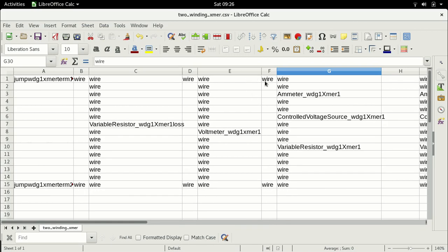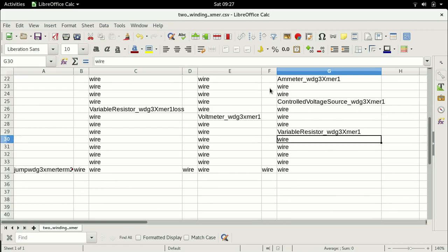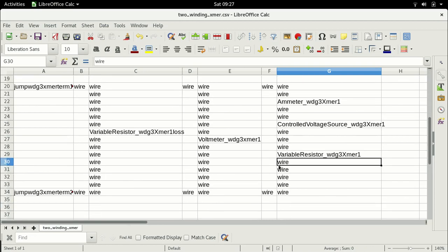Now, when the switch is turned off, the current will try to stop flowing, which means the induced EMF will oppose the cause which produces it, and that is the decreasing current, which means the induced EMF will have a negative polarity at the upper terminal. And under those circumstances, the induced EMF in this winding will also have a negative polarity at the other dot polarity, which means the positive polarity of the induced EMF is at the upper terminal.